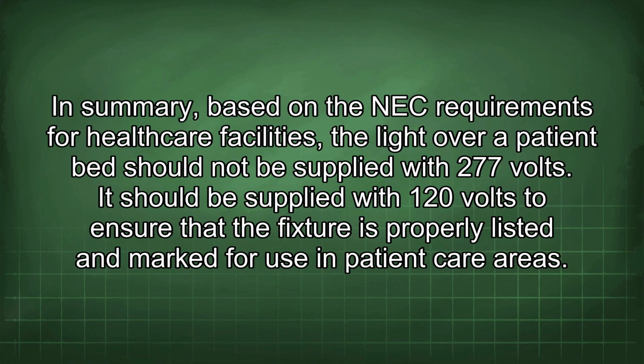In summary, based on the NEC requirements for healthcare facilities, the light over a patient bed should not be supplied with 277 volts. It should be supplied with 120 volts to ensure that the fixture is properly listed and marked for use in patient care areas.